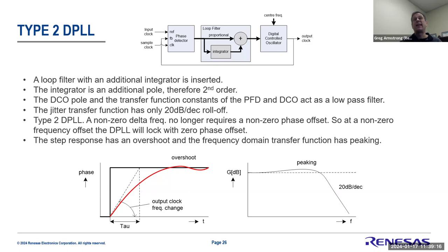frequencies from that source. And a lot of times they're much higher. Some VCOs run at gigahertz, like 15 gigahertz. So as you can imagine, when this closed loop is stable and running, it guarantees 15 billion clock cycles exactly in between each input if that was a 1 PPS input coming in. So it's a very useful mechanism to stabilize the clock and get that stability. And then if that clock is coming from a source that is very accurate, you get the accuracy as well. So you get both components using a servo.